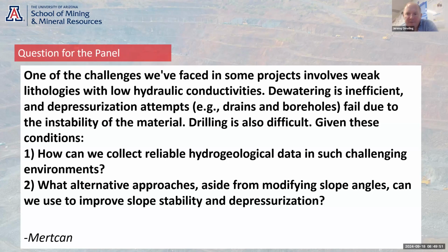They could also look at vertical drains too, right? If you can get in the right places and drill through the bottom of the clays or the weaker materials, then vertical drains can be very effective too.